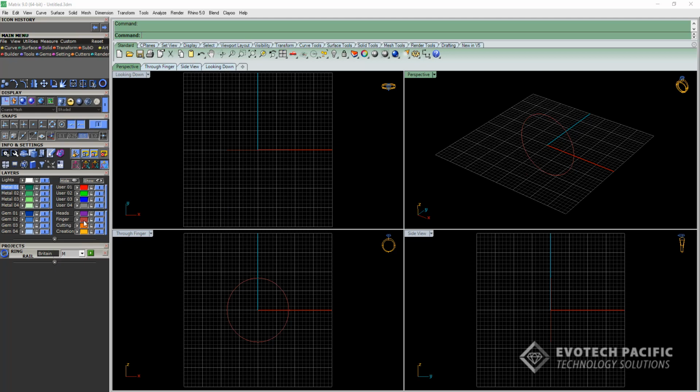If we right click this particular color, we can select it. We can also select it by dragging from right to left, and also region selecting from left to right. If you're region selecting, the entire object must be within that square in order for it to highlight. If you only select part, then nothing will highlight, only whatever happens to be within that square.